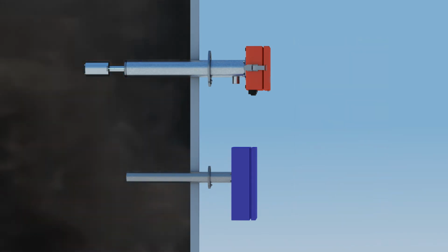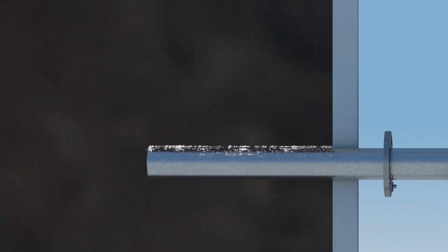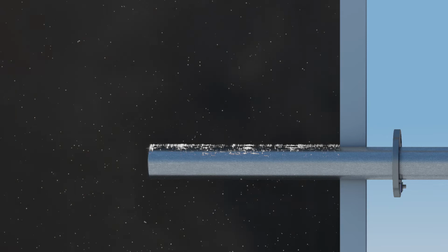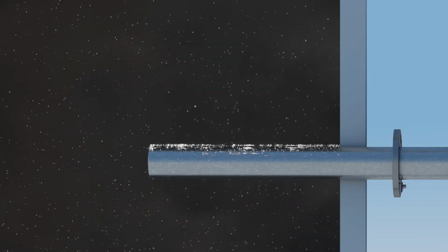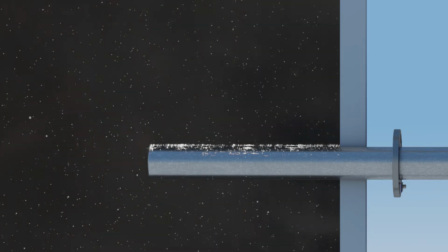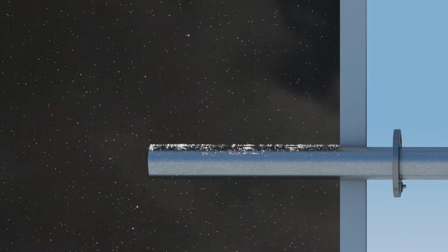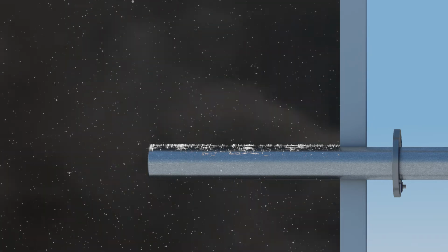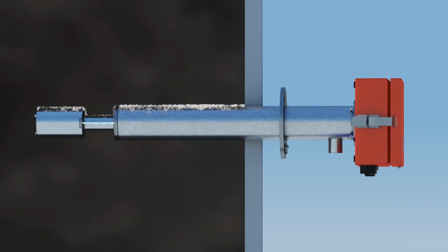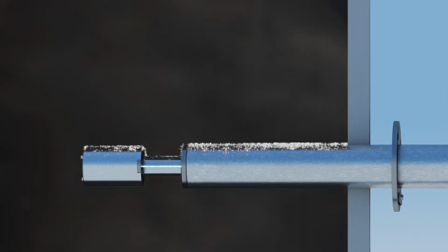Because both probes measure the dust concentration directly in the dust current, dust sediment can form on the measuring probes. Dust sediment on the triboelectrical probe can falsify the measuring result. The more dust which is deposited, the greater the measuring value is influenced. At greater dust residue, the triboflow probe usually has to be removed and cleaned at an unforeseeable point of time. With the DUSTHUNTER SP30 series, this work is to a large extent unnecessary.